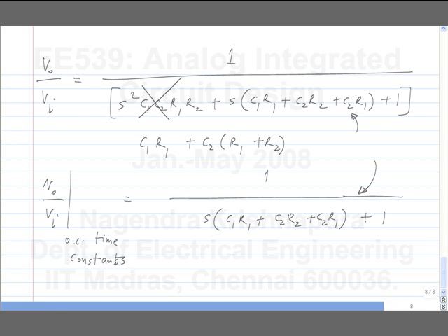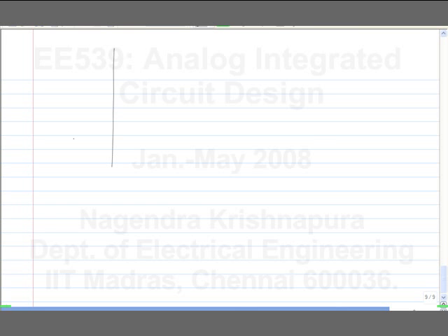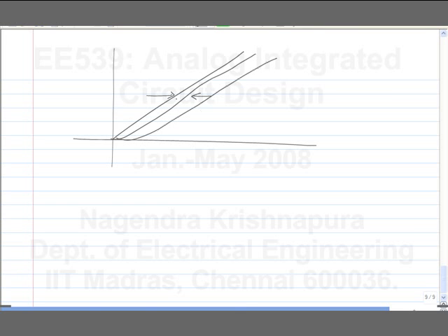When we initially analyzed feedback systems, we saw that ideally we would want the loop gain to be an integrator, or in the time domain a ramp. If we have an additional pole, we get a delay equal to the time constant associated with that pole, and if we have multiple poles, the delay for the ramp will be the sum of the delays. It is something like that, right? It is similar to that. If we have multiple time constants, then with multiple poles the total delay for the ramp will be the sum of the reciprocals of the pole values. Okay.